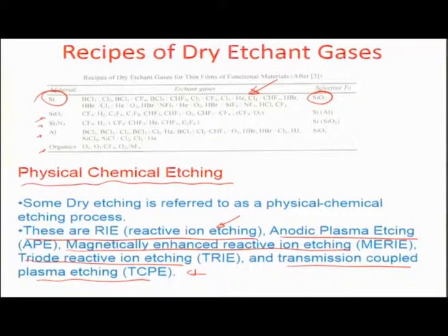So, you are using the power of the ionic state of gas, that is plasma, and on one hand you are creating bias so that the ions can impact a flat surface. On the other hand, you are also creating a small amount of chemical reaction with those ions impacting the surface, so that some etching can be carried out in this manner.